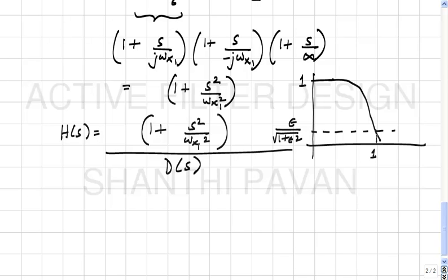So when you do all this flipping and flopping, it still remains like that, which means that this must monotonically fall from unity, and then it does this. There must be only one zero on the positive omega axis, at omega x1, and then the second zero is at infinity. Now, if you have an even order inverse Chebyshev, what do you think will happen?